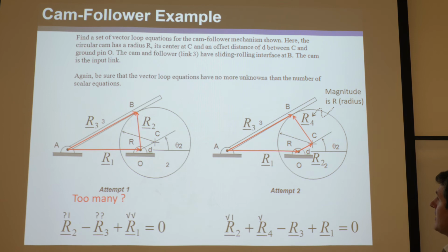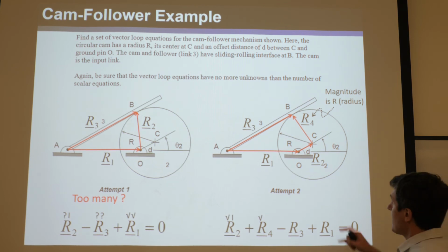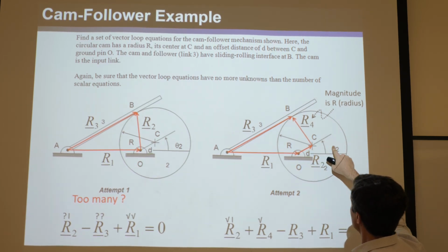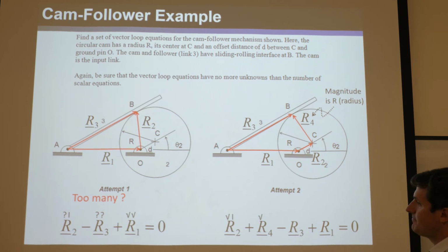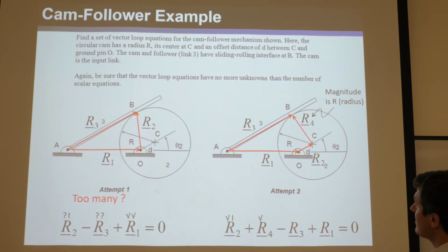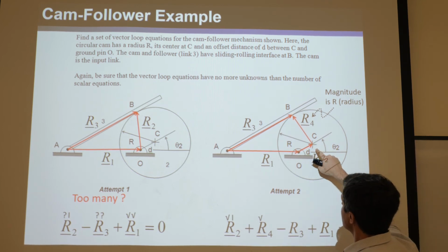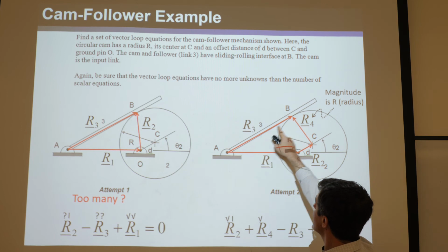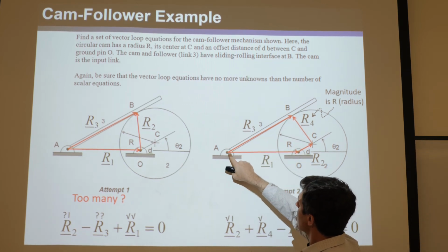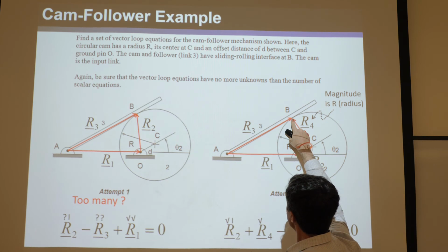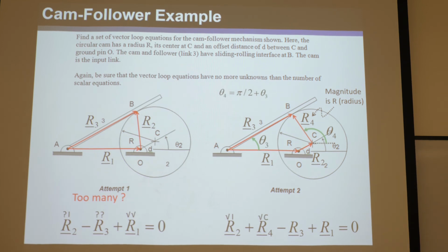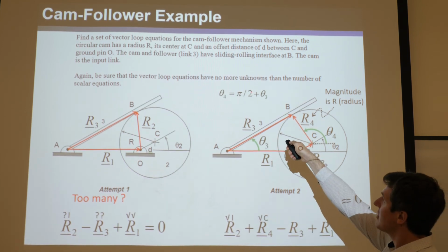We know that. Now, do we know its input angle? So remember, if this is the tail, we're going to draw a horizontal line there, and theta 4 would be this angle right there, from a horizontal to there. Do we know that? Well, no, and that is going to change as theta 2 changes. Okay, you can imagine as theta 2 changes, that's going to change, but it's going to be a function of theta 3. So remember, there's theta 3. And again, I wish that pin was moved a little over so this red line was parallel to this line. That's what it should be. Theta 3 is from the horizontal there to there. And so you can see it's actually constrained by this equation.